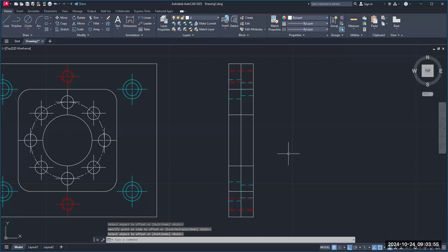Now we have to figure out what's going on here. Well, we have a pocket. This pocket goes down 1/4 inch deep. And then we have the through hole. Remember I said we're going to come back and revisit the through hole? Well, this is actually a bored hole. So go to our pair of scissors, trim, and I'm going to trim this one and this one first.